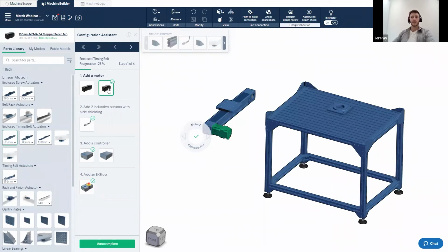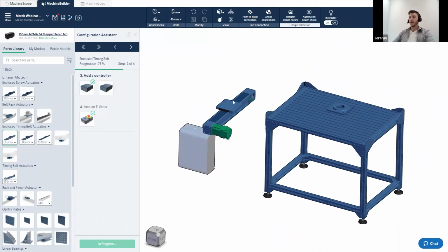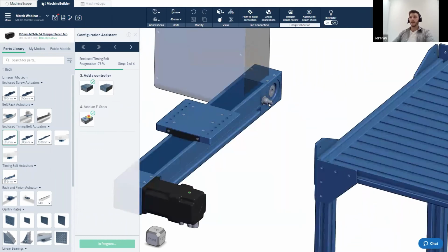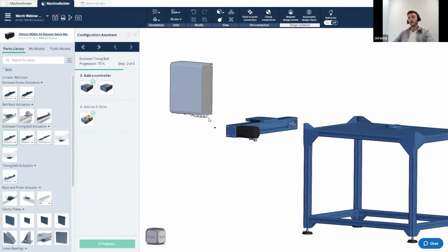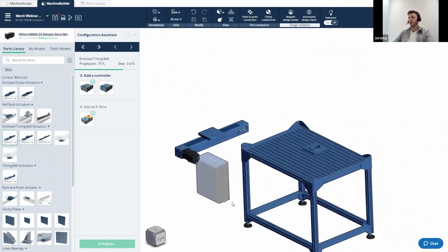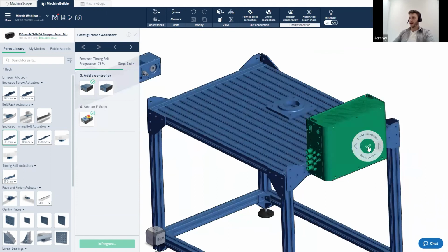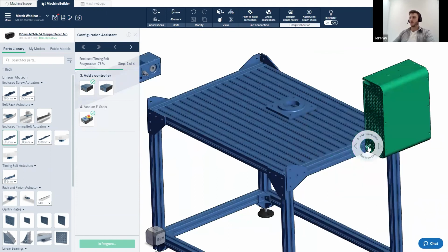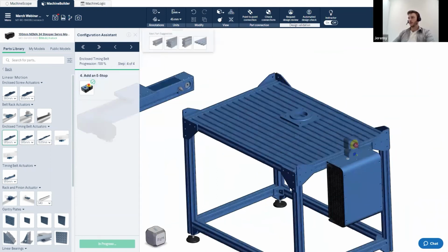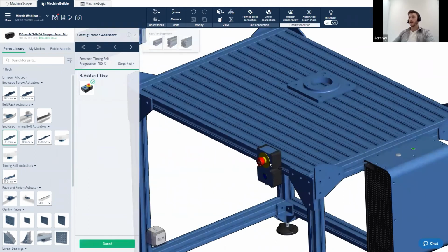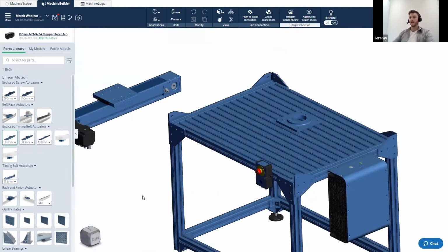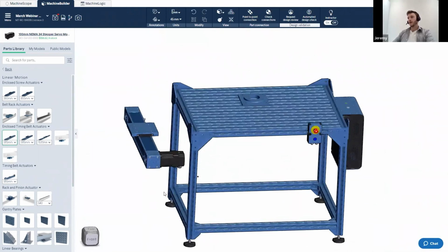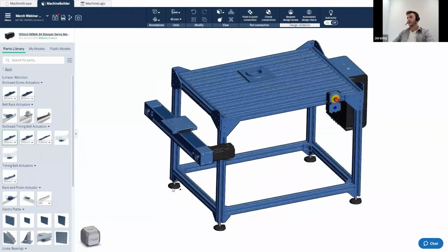In my case, I'm just going to switch over to the slightly smaller motor and press autocomplete. You'll see that it automatically adds the sensors on either end and snaps the machine motion controller, which controls our actuators, to my cursor. In this case, I'll bring it over to the outside of the structure over here, similar to my original design, cycle through the orientations, and then attach the e-stop to the front for safety. Once I'm done, I can click the Done button in the bottom left corner.